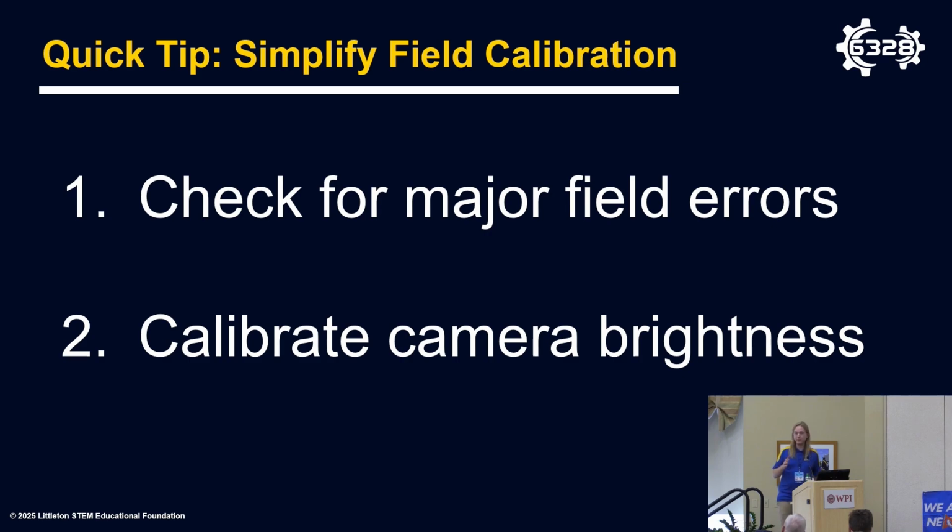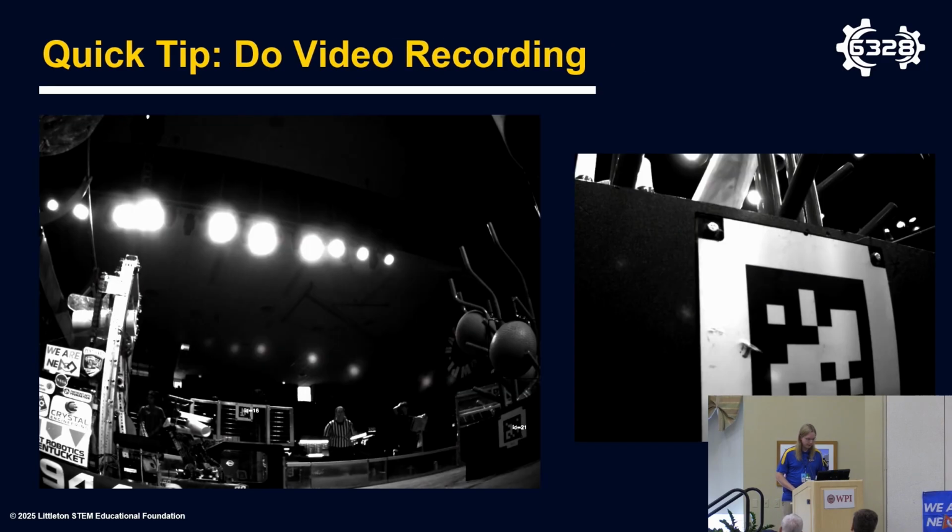Now, after our first event when we're setting up a new vision system, we actually don't tend to adjust our exposure that much. At least here in New England, lighting seems to be consistent enough that it's not a major issue, but it's always good to double check. We always do this during field cal.